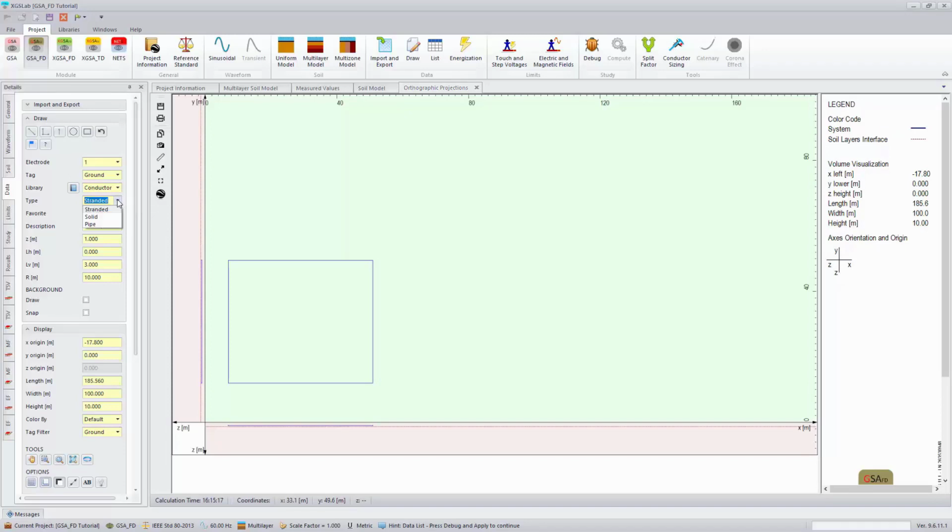It's relatively common to incorporate ground rods in these systems, so we can do that by selecting a new type of conductor property and selecting my vertical element. And this ground rod is going to use the LV value, this vertical length, to insert a 3-meter long ground rod. Here you can see in my YZ view and my XZ view, we have that ground rod populated there.